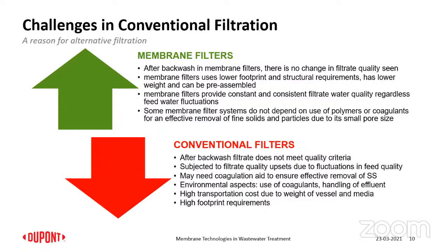It's only additional, a flexibility of the filters to achieve better removal of organics in the water, but they are not completely dependent. And there are optimized techniques where you can use coagulation at a much lesser level compared to conventional filters. So in all these respects, the membrane filters definitely score much better.